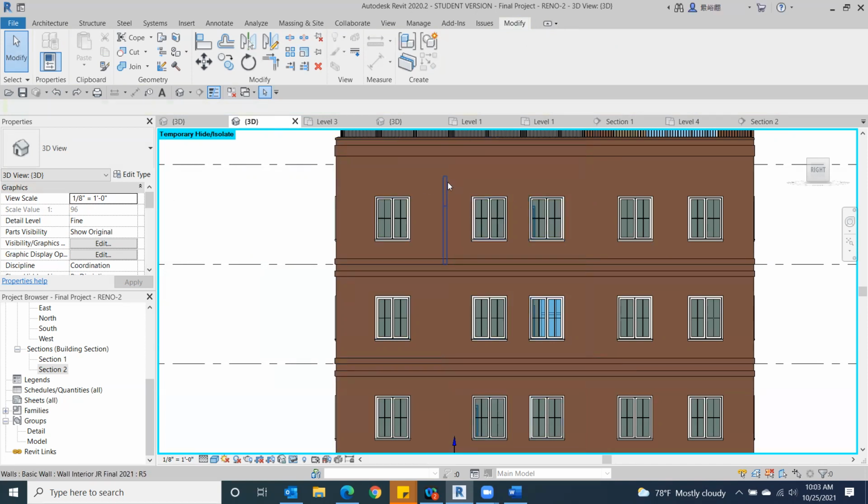That's cool. I have to look that up again because it became a pain. I was painting the sweeps and I had to go each section one at a time, one sweep at a time. You don't have to paint the sweeps. You should be able to just use the same material. You can change the material, and it does it at the same time. Oh, yeah. Well, too late. Yeah, you don't have to paint them. You can change the material when you create it. That would work as well.